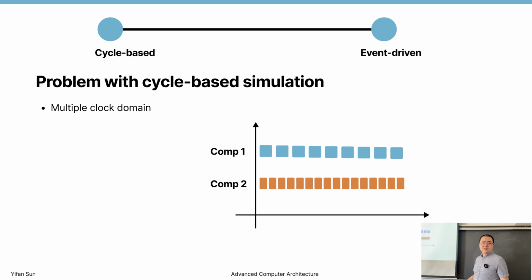It's a waste of energy. So when sleeping, you want to put it down to the lowest energy. Then whenever a request comes in, you can increase the frequency. Even with a booster clock, you can run at a much higher frequency, then go back to the regular frequency.